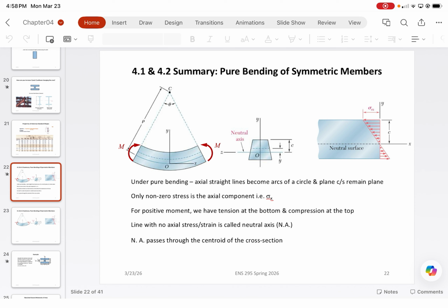Yeah, because the way that I'm planning on getting this to work is it's going to have a little mechanism like this with a bearing plate right here that's going to basically bear onto the road deck. So you kind of want to strategically place your stringers to be able to handle the load, because the road deck itself, unless you make that the primary load bearing element, is not likely going to be able to handle the load unless you make it very thick.